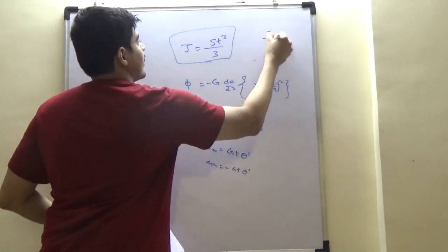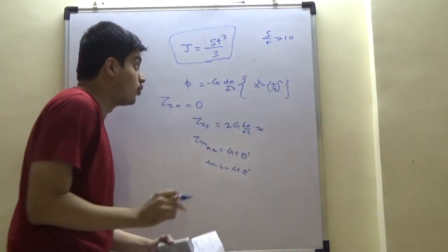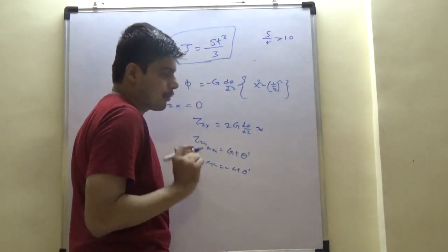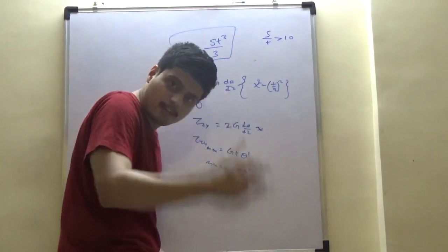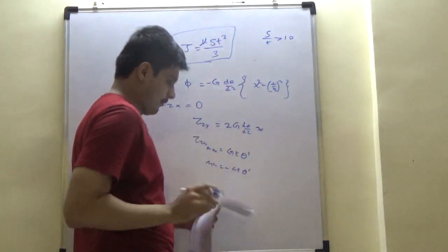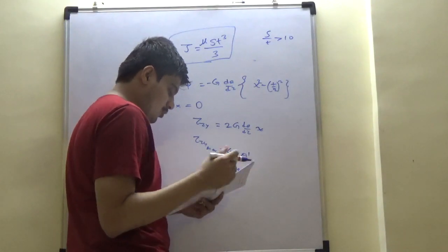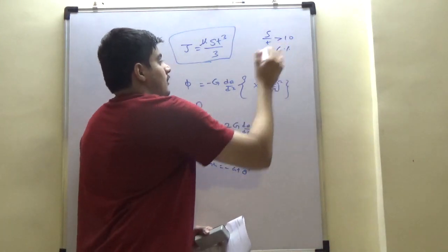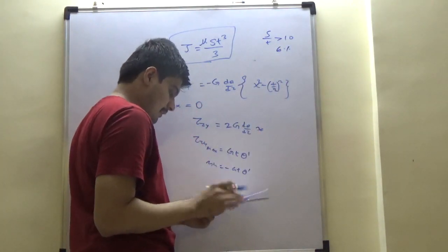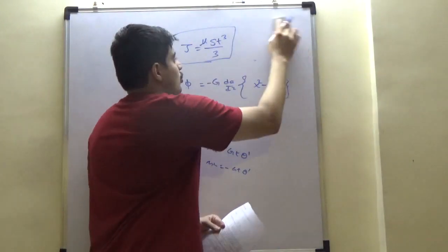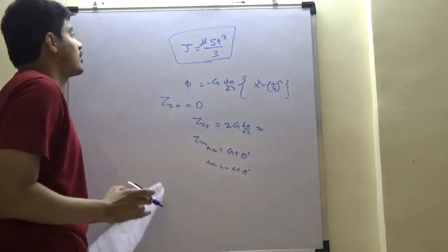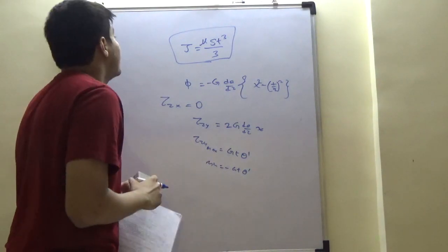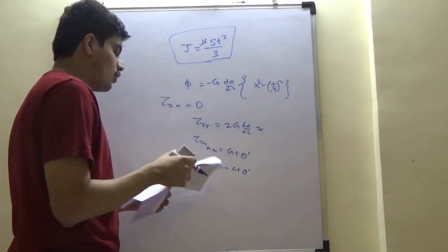And we have said s by t greater than 10, this holds very, very true. In reality, in aerospace, when you start building this first approximation, Prandtl immediately suggested himself a correction factor mu. Because when the ratios are in excess of 10, error is only about, so if this is about 10, error is 6%. When they become slightly smaller, they use this. So this is reference value. So for different s by t, he gave these correction factors for inertia, so that experimental values will start matching. So we have defined phi, we know the stress variation, we know the inertia.